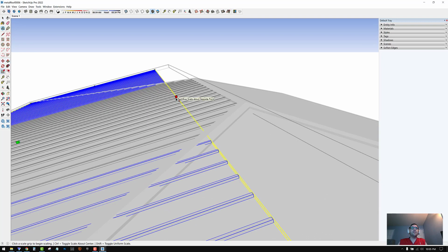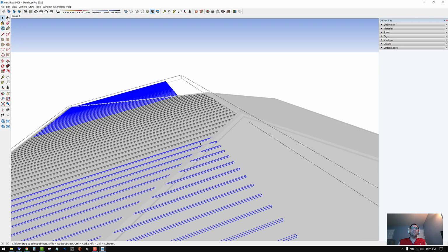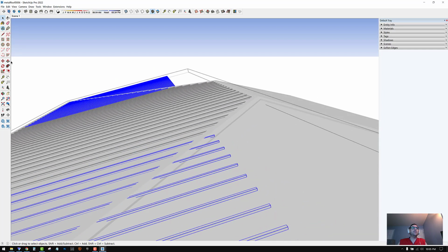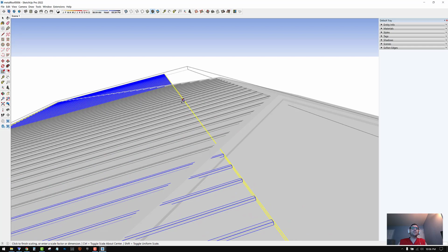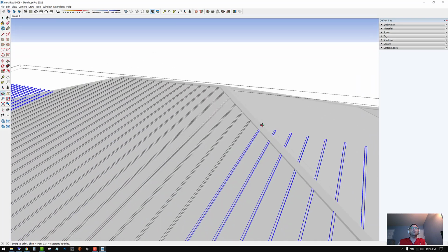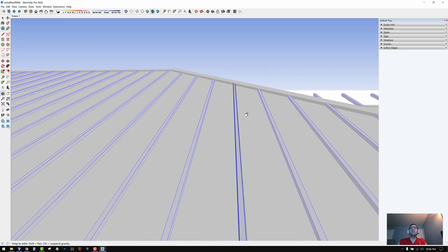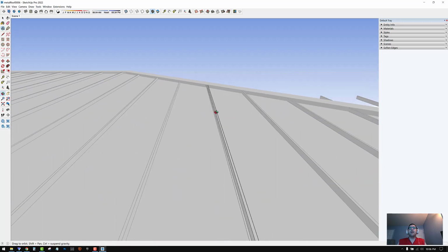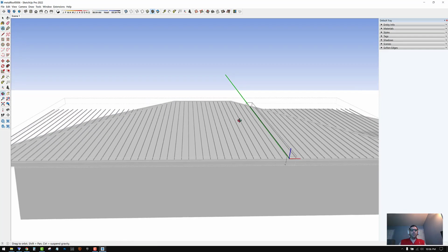And you might be thinking, why go through all this trouble to make these objects so nicely modeled? Why not just draw the lines right on top of the roof and just draw them around the whole building? Well, I'll tell you why. Because someday, for one thing, it's a lot cleaner to do it this way, but also someday you might want to change things, and you're like, oh, I think this ridge should be a little bit skinnier, so if I just go like this, now I made all of the ridges skinnier just by making one skinnier.